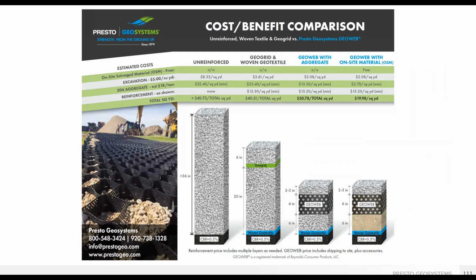It always comes up on cost. Like I said, we're always going to be less than other geosynthetic solutions, especially if you can use existing recycled and sandy materials, low cost infills with low friction angles. When you look at grids or geotextiles alone, they do require that high friction angle lockup.